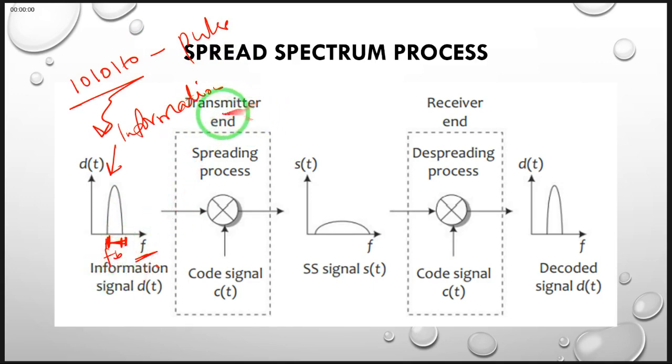When this is taken through the spreading process by the spread spectrum modulator, we get a spread spectrum signal that is increased in bandwidth, which we can now call FC. The bandwidth of this spread signal is way bigger than required. The channel that we are transmitting through may be a wireless channel, and we had seen that it requires a bandwidth of value FB.